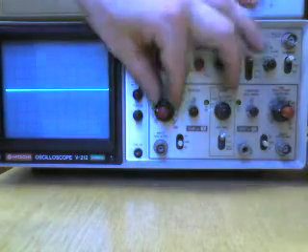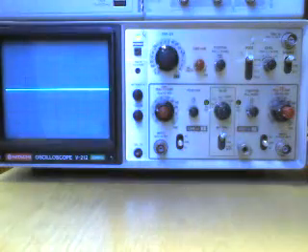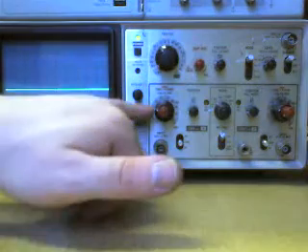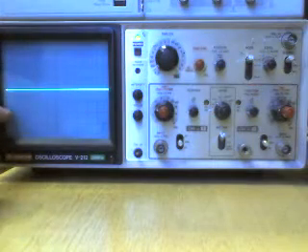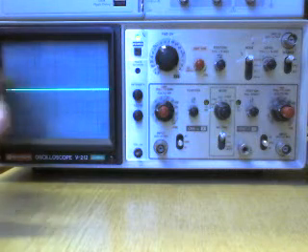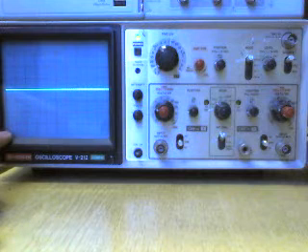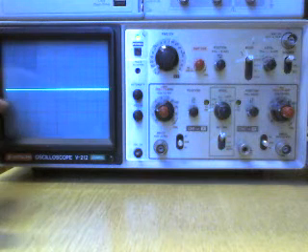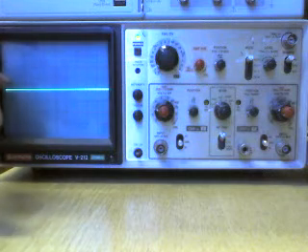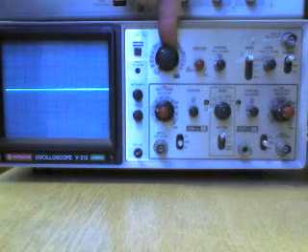Now you can change these. These are your linear increments, if you like, just like what we have on the graph, the steps that your graph goes in. So if this is set to 1 volt per division, each one of these divisions going vertically is 1 volt. So 1, 2, 3, 4 volts it can swing negatively, and 1, 2, 3, 4 volts it can go positive. Same thing with the milliseconds.